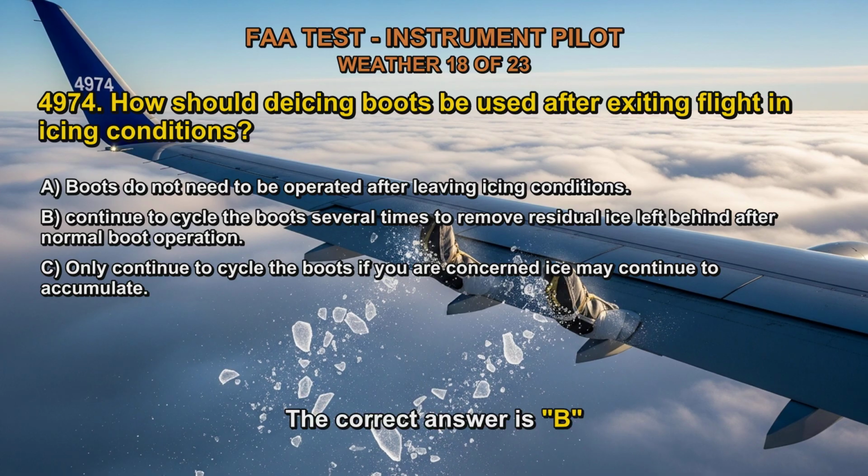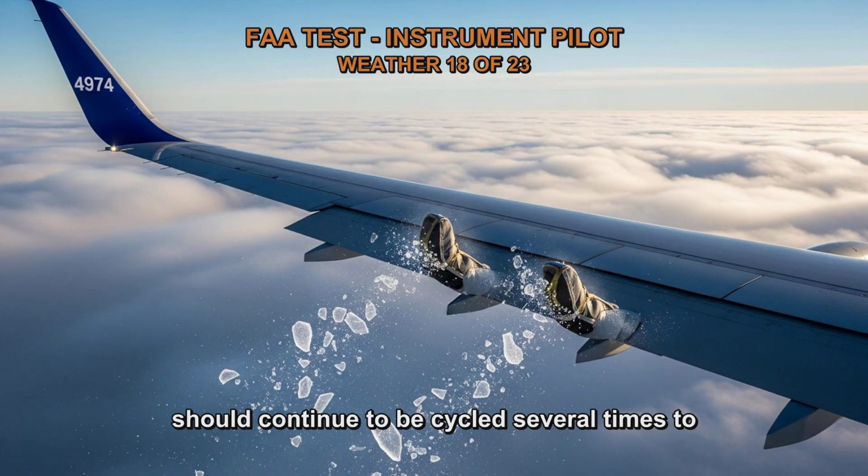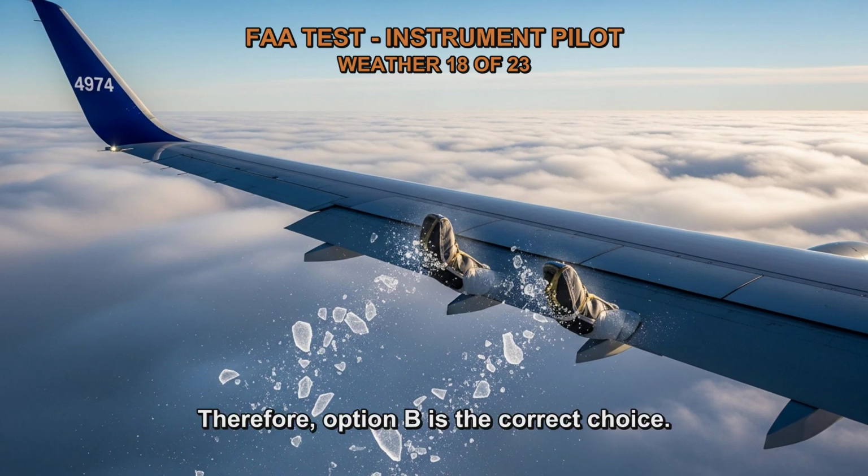The correct answer is B. After exiting flight in icing conditions, de-icing boots should continue to be cycled several times to remove residual ice left behind after normal boot operation. Therefore, option B is the correct choice.